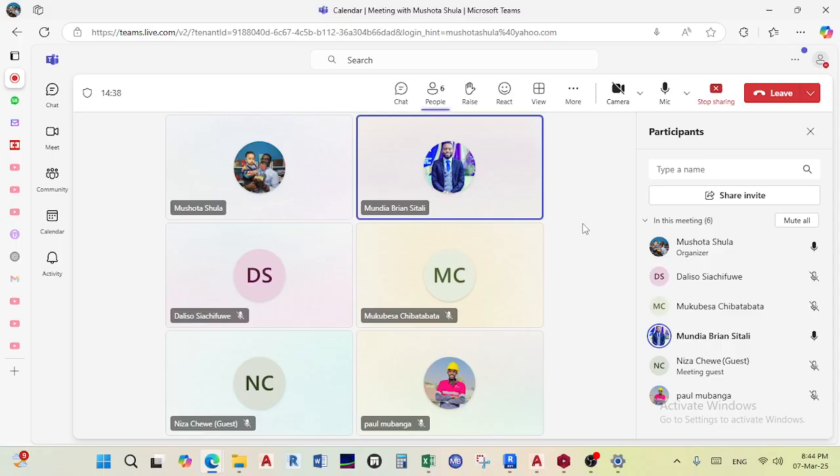So the construction joint is basically you want to do an undertaking and have it terminate somewhere, then you continue. It's a way of phasing a continuous process of construction. You know the hydration process of concrete is within a short window. So if you are undertaking construction continuously and there's an interruption somewhere, you have a potential of having what is called a cold joint. That's what we avoid having. That's why we do construction joints.